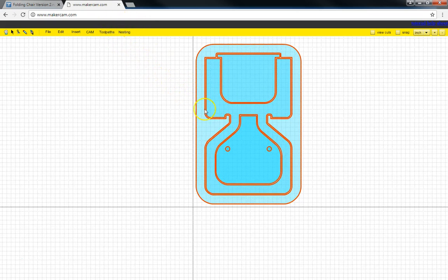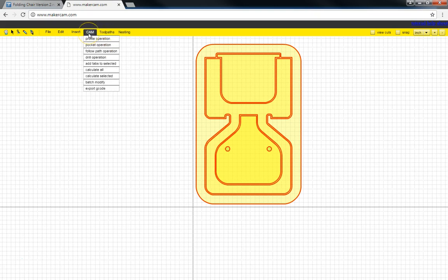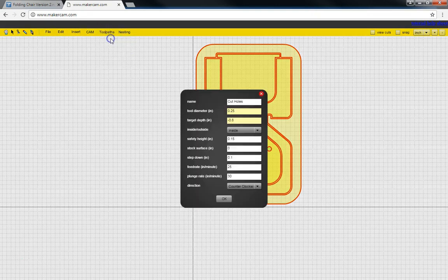Now the main thing that you're going to get out of this is tool paths, okay? The reason I selected theirs instead of making a fresh one was because they have already selected all their tool paths. They made these tool paths, and all we had to do was adapt them slightly in order to actually work. Now, the way that we would adapt our tool paths, you click on it, and it brings this up.